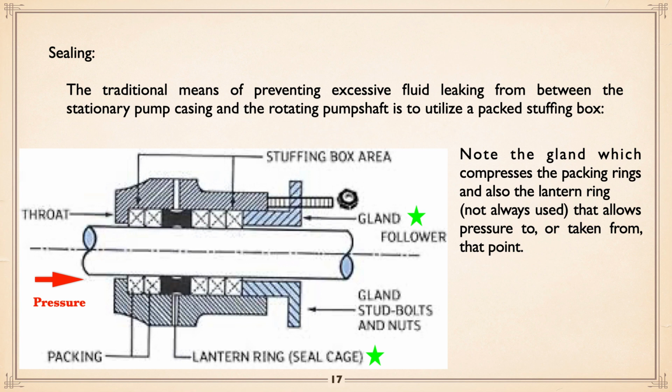Now, it's not uncommon to have a lantern ring in the middle, and there are games you can play if you have a lantern ring in there. You can use it to break off pressure or to put in a flushing fluid if you want. And again, we'll get into that. Okay.